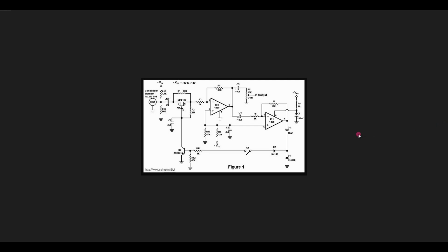Here is the classic feedback style compressor. You have an op amp, you're amplifying the audio and it goes out to your radio, but first you detect it, send it back to an amplifier that controls a field effect device that's a variable resistor in effect. So you have a variable gain amplifier. This closed loop system is a typical automatic gain control system that's used today.